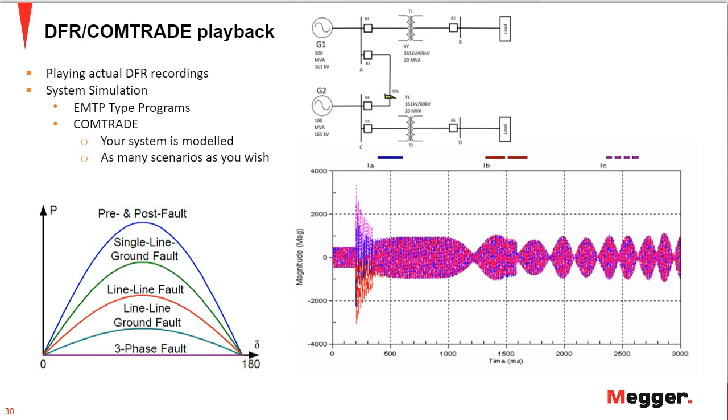and that you can use for your power swing element testing, you have to actually simulate the system, and you have to simulate different conditions on the system, and you have to simulate different types of faults at different positions on the system, and then you have to create a database of cases that is going to be good only for one condition of the system, because as the system evolves, as time passes, the loads are going to change, the impedances of the system are going to change, the system itself is going to change a little bit.